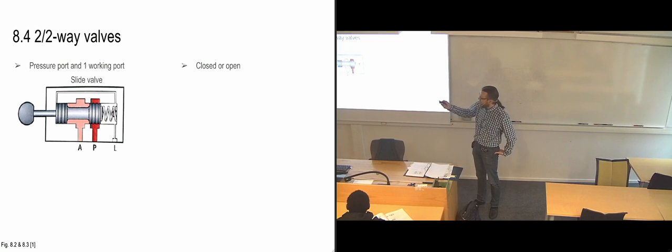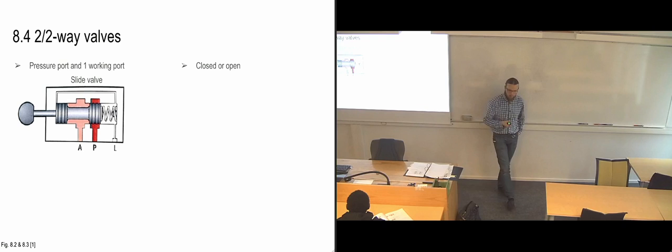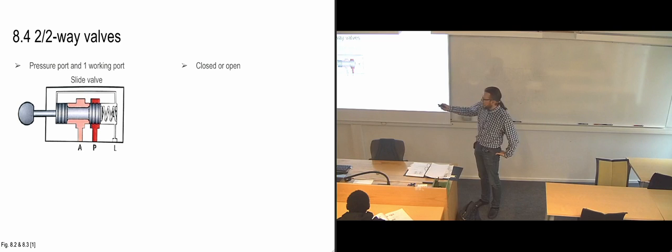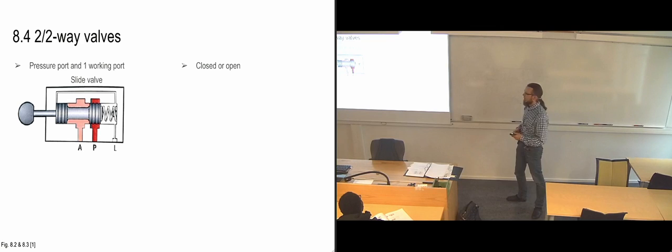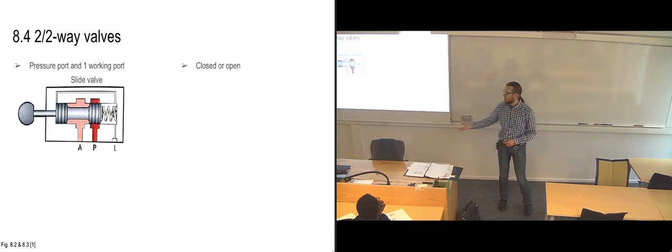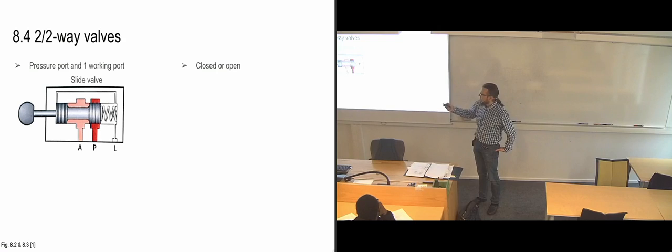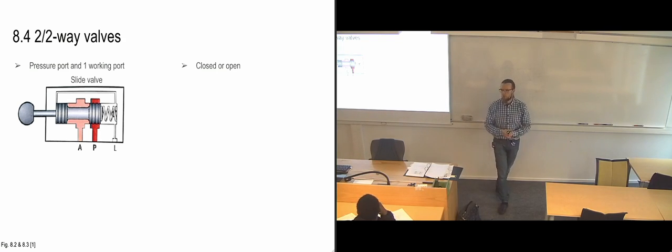That's going to move across here, and then we're going to get a leakage line back to tank. But the leakage line, as you can also see from the cross section here, is not made to handle large loads. You're not designing the leakage line to take a certain capacity. It's been designed with regards to the expected amount of leakage past the piston, which isn't really much. A few drops here and a few drops there, basically. But there is going to be some fluid there, so you need to remove it from the system.